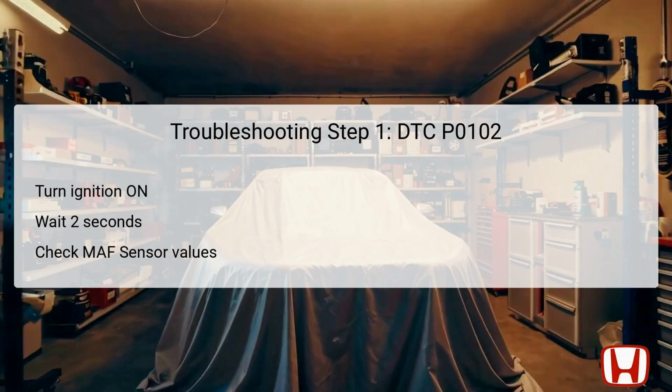If the readings indicate 0 grams per second or a voltage of 0.1 volts or less, this confirms that there is a problem with the MAF sensor's operation. However, if the readings are accurate and fall within expected parameters, it may indicate an intermittent failure or another underlying issue. At this point, further inspection of electrical connections and terminals related to the MAF or IAT sensors and the PCM should be considered.